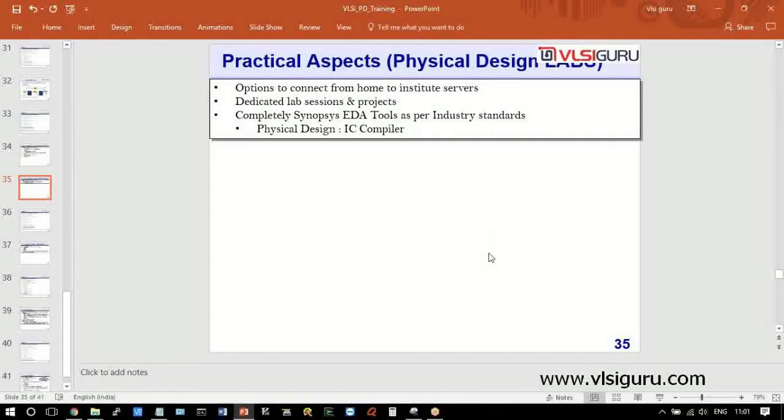Like you'll be creating PMOS, you'll be creating NMOS, poly crossing the active region, creating a P transistor and N transistor. So one more thing which I wanted to know, you all know what is CMOS, right? CMOS. Why is it called CMOS? Exactly, it is a combination of NMOS and PMOS. That is why it is called a CMOS. But what does that C stand for? Complementary. Okay, good. So everybody knows the word.